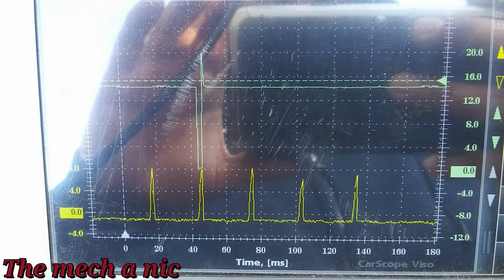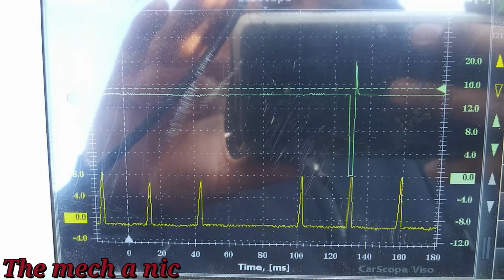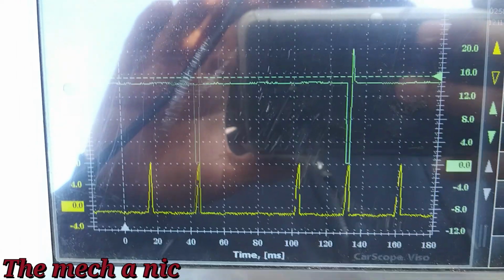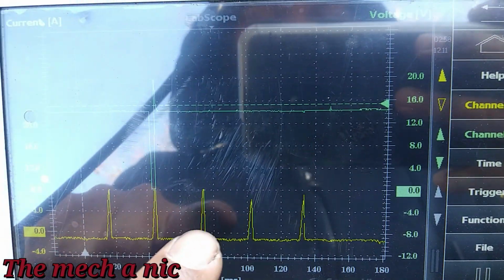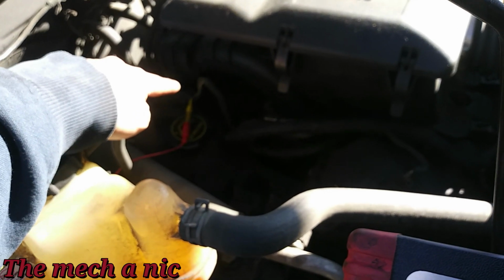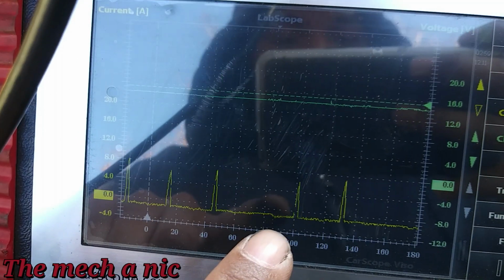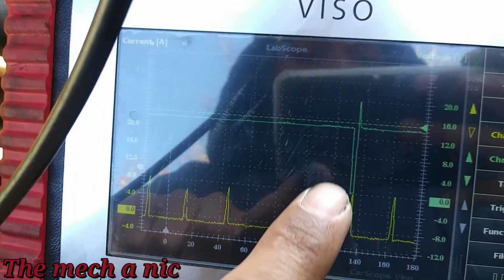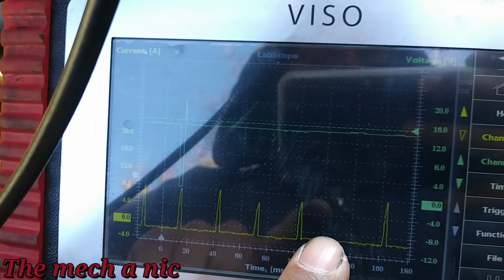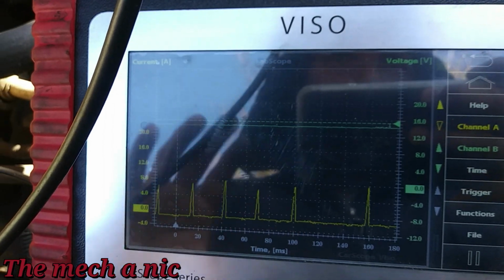And if you look at it, the wire I picked, or the fuel injector I picked, is not lining up with the spot that's missing. So it means all I have to do is go choose a different wire, and I'm just going to go through each of them until the injector number 4 lines up with that one that's missing whenever I disable it. So I hope all of that makes sense.